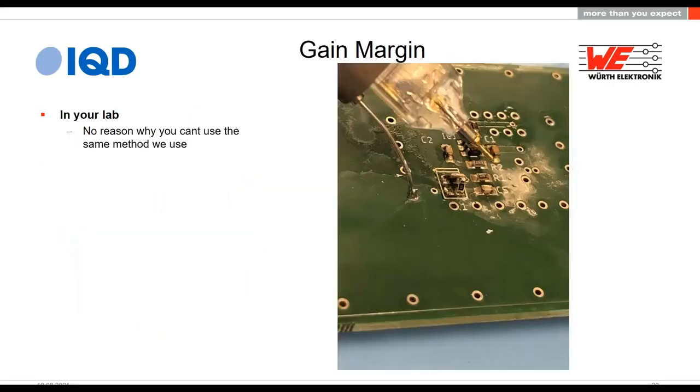Okay, the final measurement that we made was the gain margin. You remember that we added that fixed resistor in series with the circuit, and we kept doing it and kept making sure the crystal started up. And when it got to the value, then that was our negative resistance ratio.